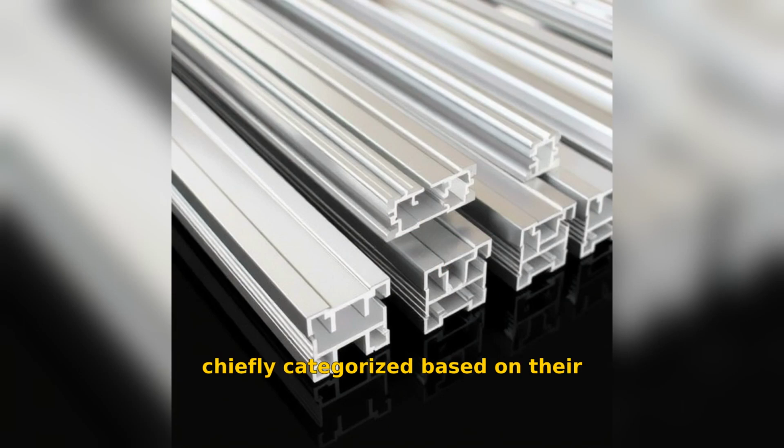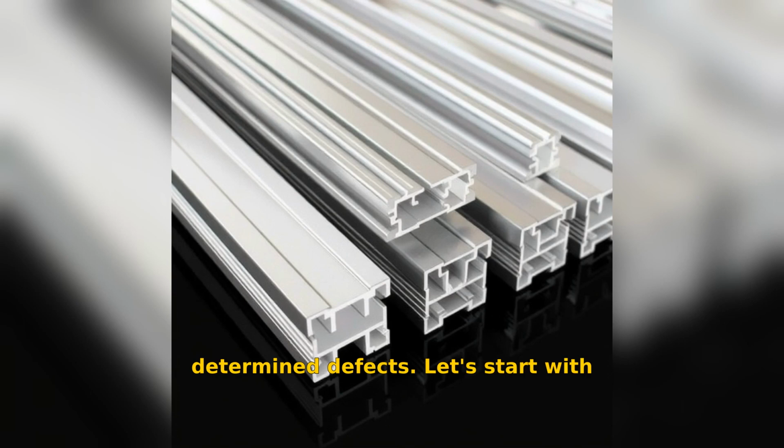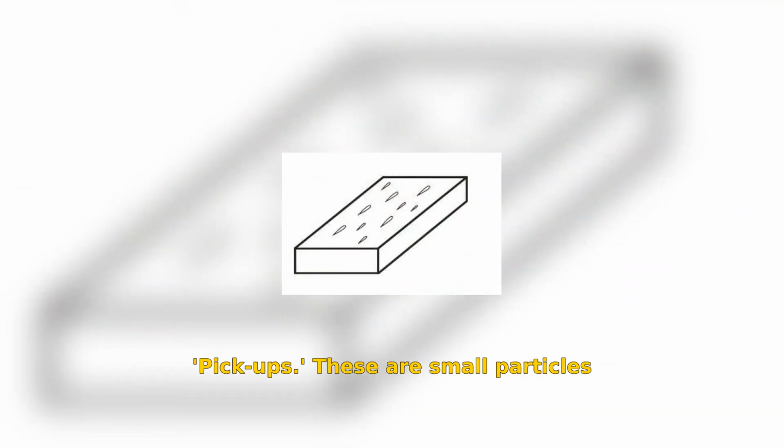Surface defects are chiefly categorized based on their origin: extrusion press-related, metallurgical-related, and mechanically determined defects. Let's start with extrusion press-related defects. First up is the pickups. These are small particles of aluminium and oxides that tear away from the surface and settle back on it, forming comma-like shapes in the direction of extrusion.